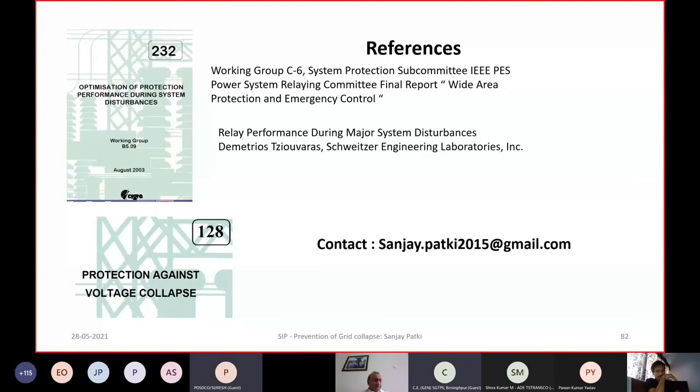In the auto reclose process, what is the effect on the other healthy phases? Suppose we have auto reclose in R phase, then during that time, does some load of that particular phase transfer to the other phase? That is my question. No, there is no effect on the other two phases, but the parallel circuit will have an effect. If there is a parallel line, A phase current doesn't get transferred to B phase or C phase. The A phase current will get transferred to A phase of the other parallel circuit.